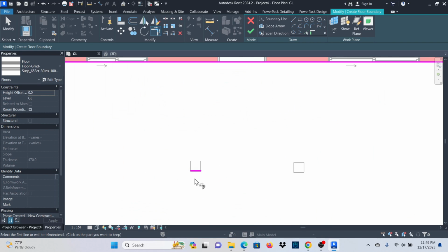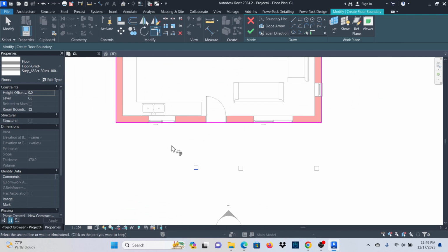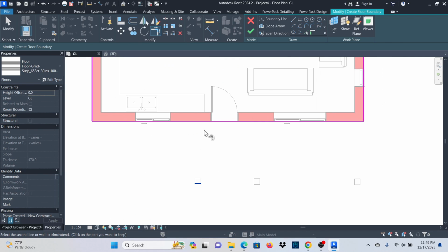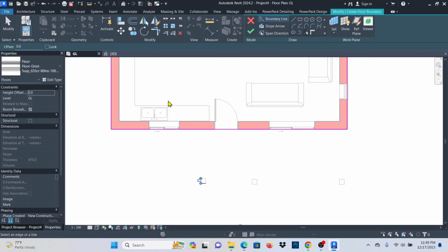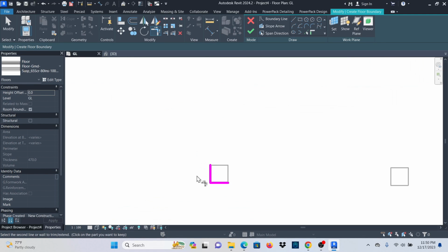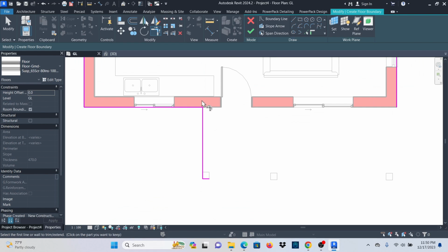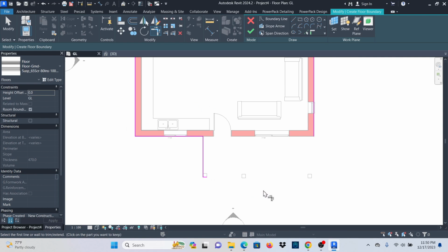I can also go ahead and pick this line. Which other line? Oh, I also need to add the vertical one, so I'll click on pick this one right here and add one. Then I'll click on trim. Then I can pick this line, and these lines have to be perpendicular to each other. They should be horizontal and vertical, or at least at an angle, so that you can trim.